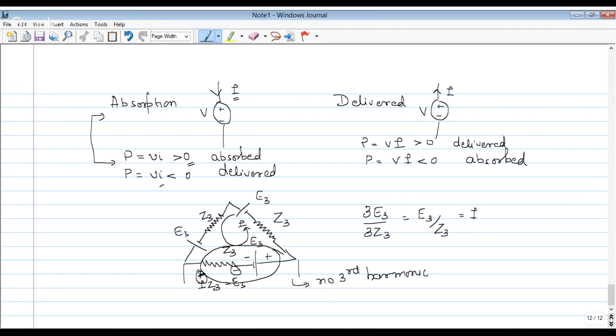Now, what happens in a 3-point starter is what it is saying: the motor may stop at low speed. Correct, absolutely correct. Actually, I have answered it incorrectly. The answer should be A. The speed of the motor will determine the EMF, because EMF is directly proportional to speed. If the motor speed is low, EMF is low, due to which flux will be dropping in a shunt motor.